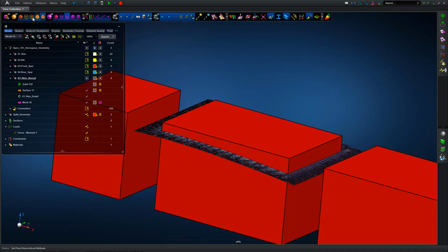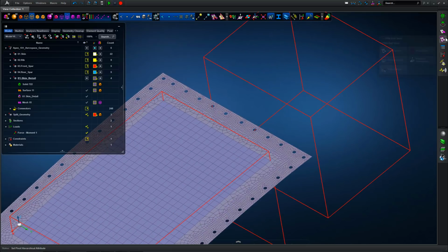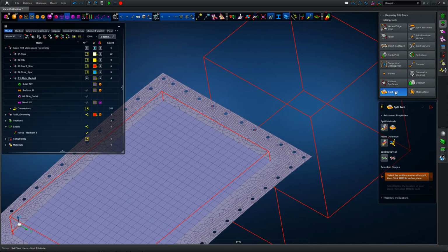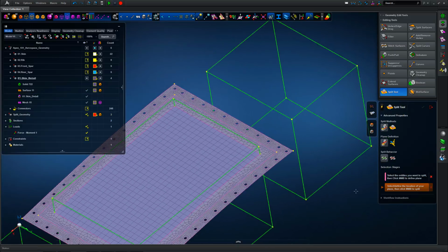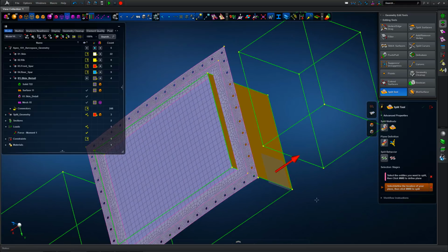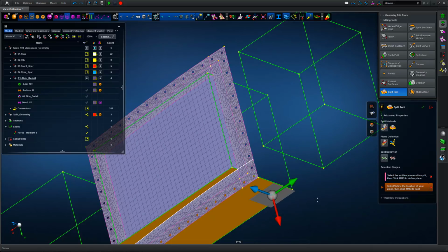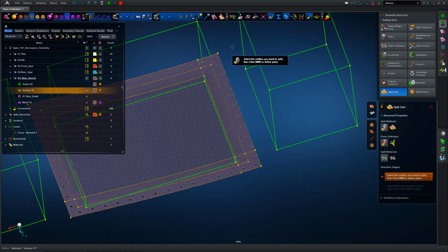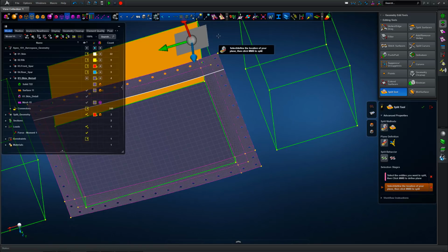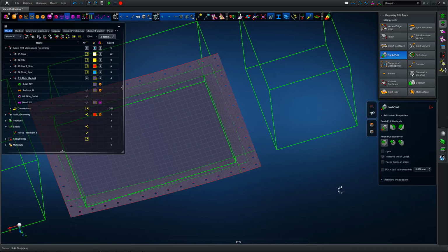Okay, so similar to how we split the panel of interest for the mesh transition, we're going to use a similar technique to split the underlying panel to allow us to define some patch plies to strengthen the regions where we saw potential failure earlier through the original laminate. So it's a simple case of picking the panel, picking the surface of the 3D cube or 3D shape that we've got access to, and then we can chop the panel up.